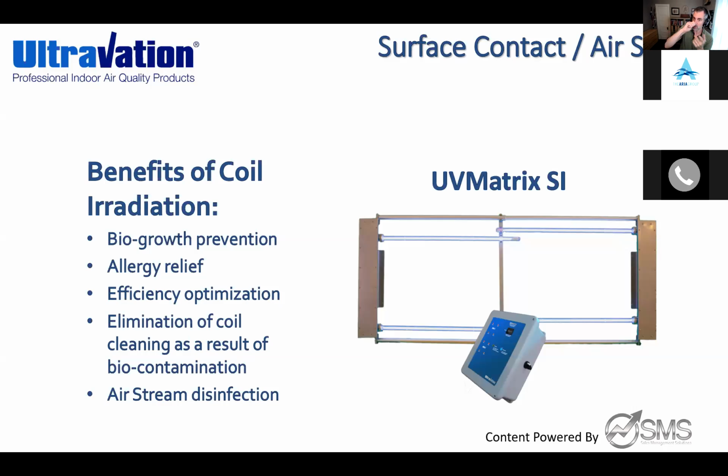Sometimes, like the library I talked about earlier, we ended up putting six racks like this in there because they had stacked coils. It was a big library with huge coils, and we had to do six stacks of these in all four units. So it was a great job. That gives you your coil coverage, and you still benefit from some airstream disinfection as the air is passing through. But you really should have an airstream dedicated solution as well.